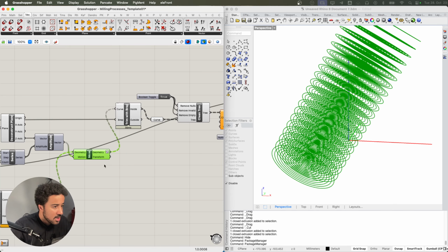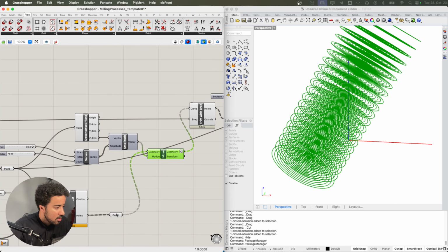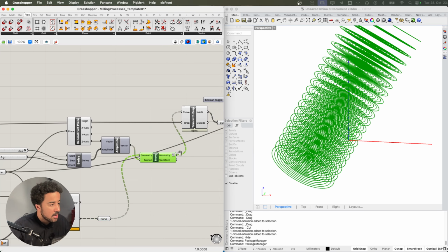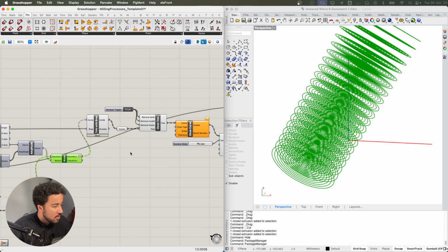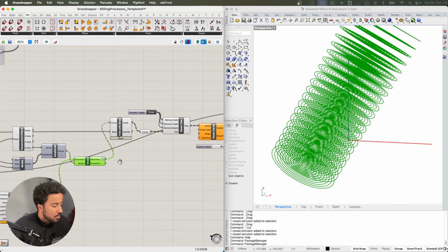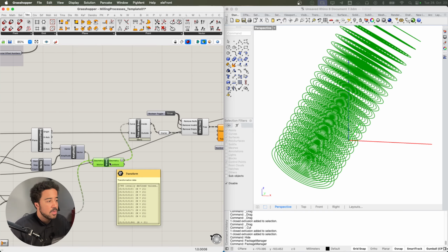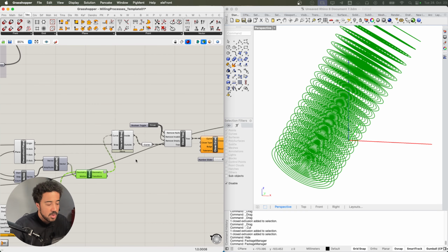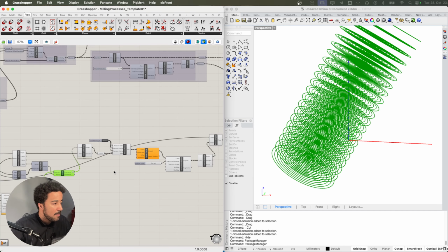This probably wasn't enough. I'm not entirely sure how the list looks, but this is probably just a step too much, and this tutorial is already getting kind of long. But it is important to look at the order of lines and curves when we're sending them to a machine, because of course we want to start from the top and work our way into the material and not crash into the material and work upwards.